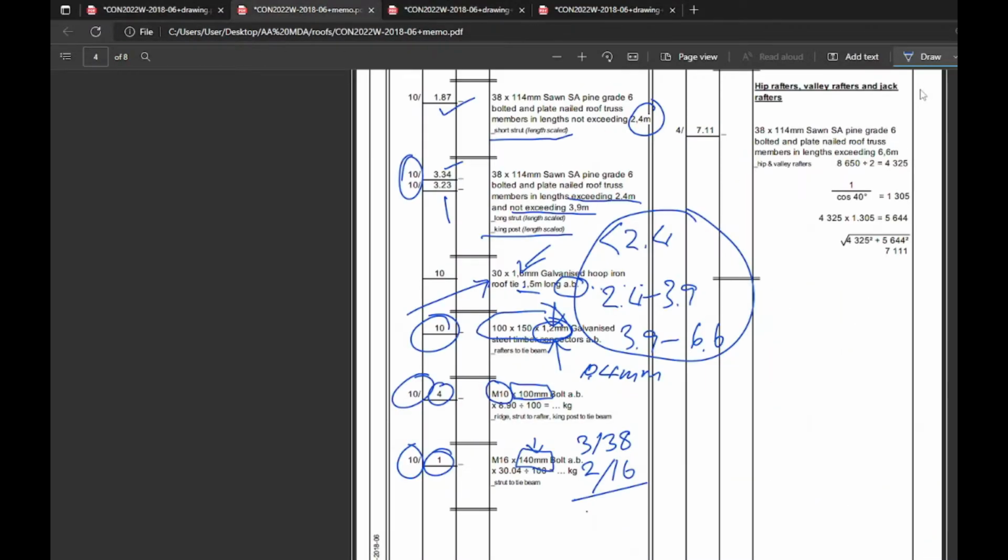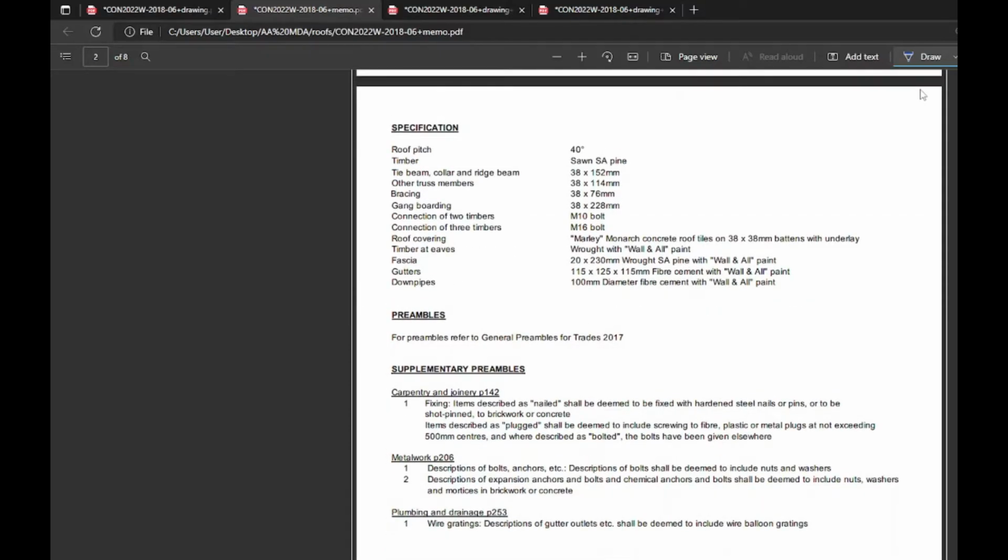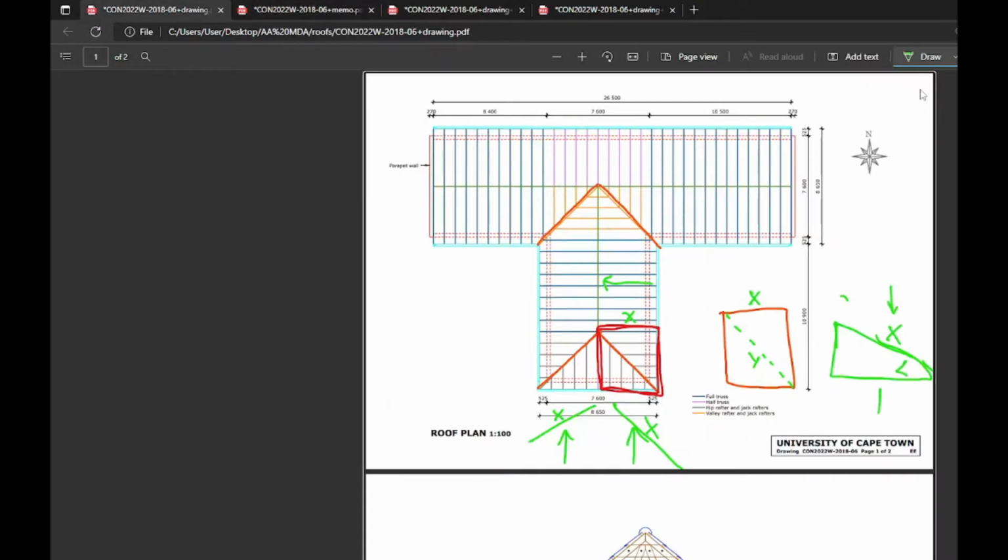So let's bounce back. We need to find out the pitch of the roof, 40 degrees. Okay, there it is. So it's given as 40 degrees. And from here, it's a pretty basic trick, but you need to keep track of what you're calculating. So we're currently doing x leading up to the apex in a straight line, so perpendicular to our ridge. First, use cos, and from high school, adjacent over hypotenuse. Do some rearranging. Okay, so adjacent was 1. So what it ends up being is 1 over cos 40.